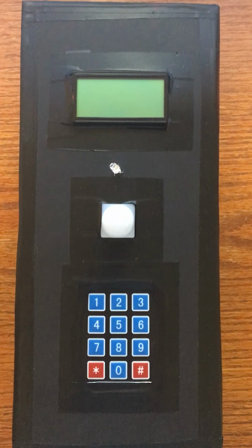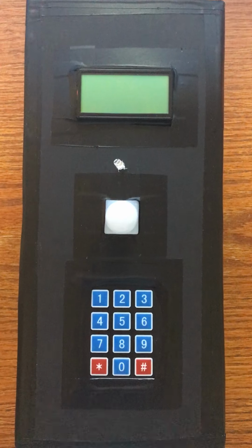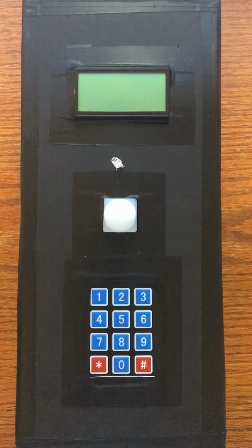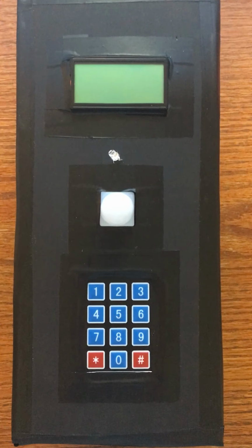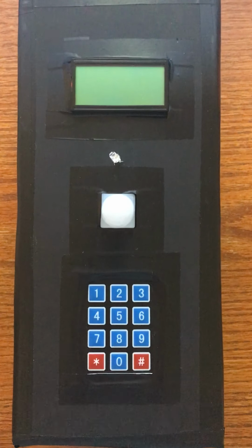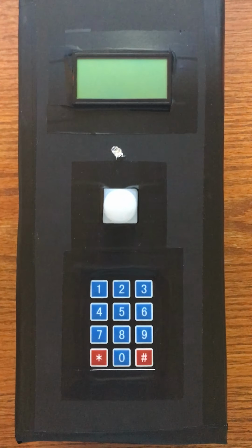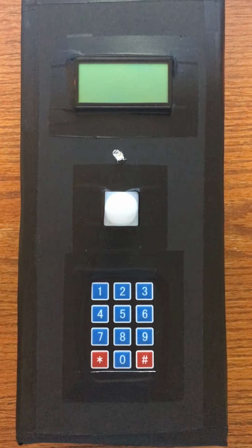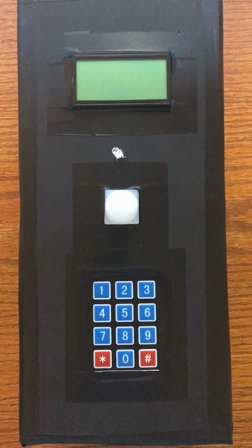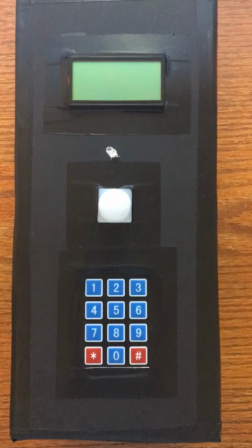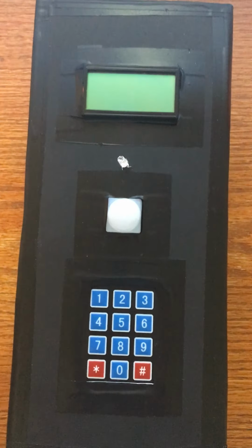After the countdown stage comes the alarm engage stage. During the alarm engage stage, the software architecture clears the display and sets the cursor at the beginning of the first line. The software architecture then displays the message, alarm engaged. Next, the software architecture initializes the keypad and activates the motion sensor using ADC14 and its interrupt service routine. If the PIR sensor detects motion during the alarm engage stage, this triggers the intruder detected stage.